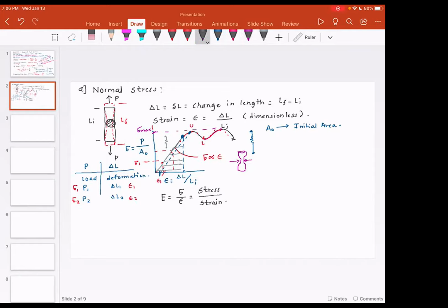So I need to write this down. So strength is the maximum stress a material can withstand. So what happens is you exceed the strength of the material, and that causes the failure of the material. So you will see for a ductile material, you have cup and cone type of failure, and then the material separates. So elasticity has a life cycle to when it starts to lose its elasticity. We test this in tensile testing.